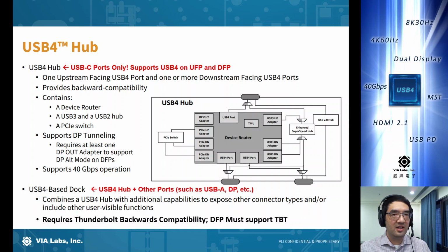To take this concept to the next level, we now have the USB 4 based dock. The USB 4 based dock is essentially a USB 4 product that has USB 4 downstream facing ports, and it has other port types. You can have some USB Type-A's for your legacy connections. It could also have a DisplayPort or maybe some other video outs. So a USB 4 based dock is a very specific term when it comes to USB 4.